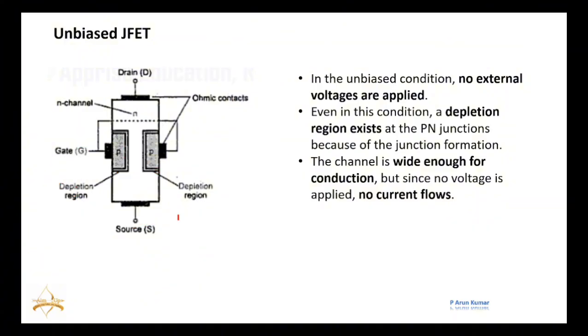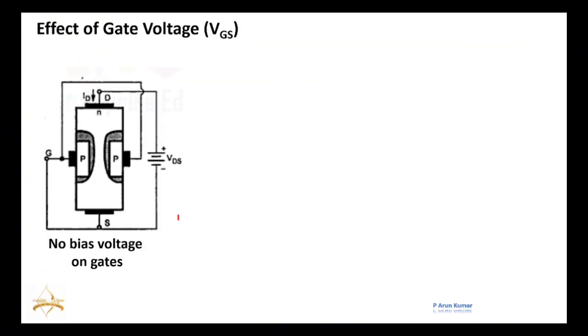So if you see this one after the other, in the case of VGS equals zero here, I'm saying, here I'm not giving any kind of VGS voltage. This VGS is zero here. I'm not giving anything. This gate is directly shorted to the source. So by applying this VDS voltage, these electrons can move from source to drain, and maximum channel is available. Initially, maximum channel is available.